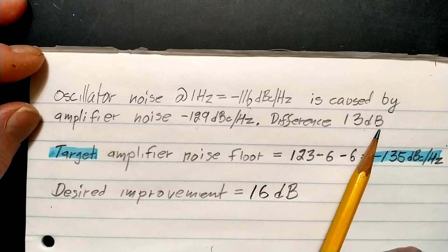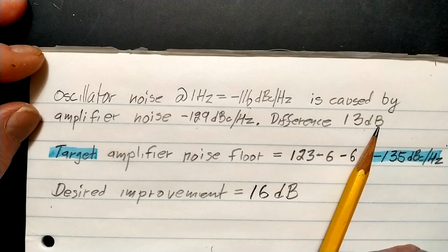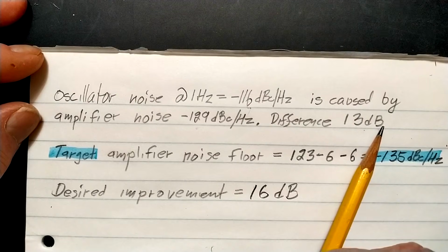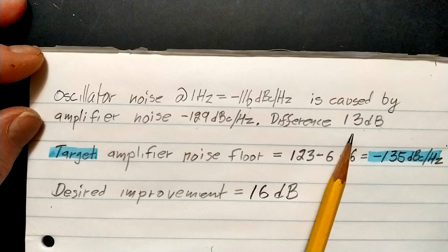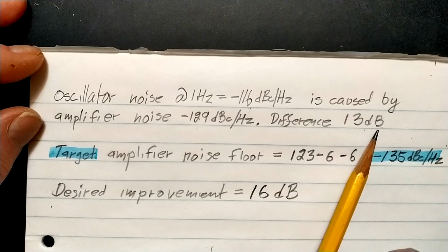This may be influenced by how the coupling to the crystal is arranged, because the power output from the limiter is a little bit too low, so I may have loaded the crystal a little bit too much. If that is true, this difference would be a little smaller if I had more power from the limited output. But that's a small thing.